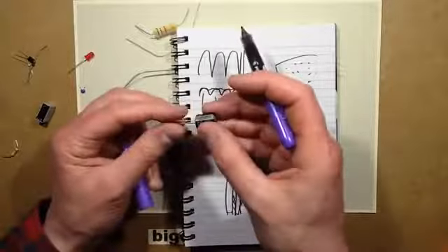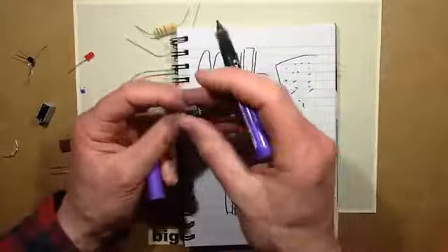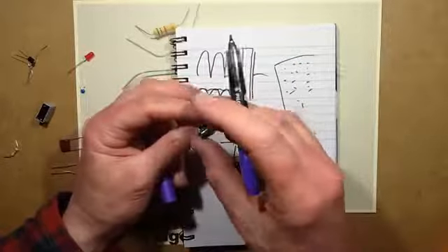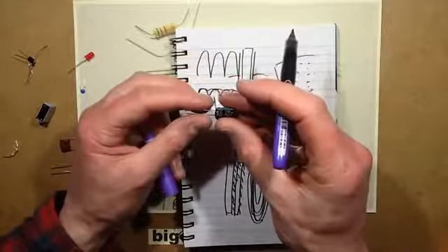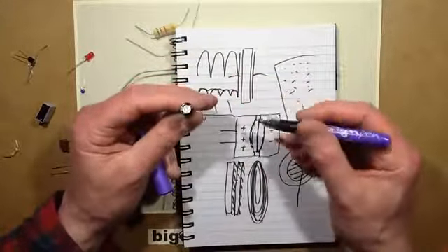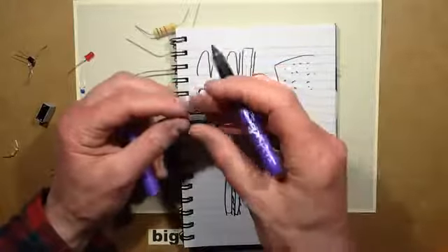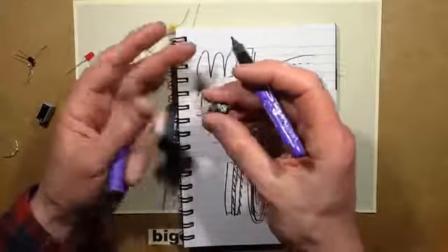However, that's more of an issue with modern electronics, because whereas in the old days these capacitors only had to deal with 100 Hz or 120 Hz, just mains frequency rectified, nowadays the capacitors have to deal with the output from switch mode power supplies, which is thousands of hertz, tens of thousands of hertz, and it means that they actually heat up and they dissipate more energy.